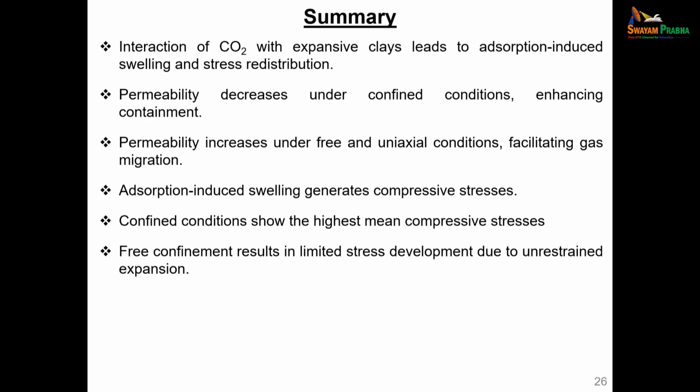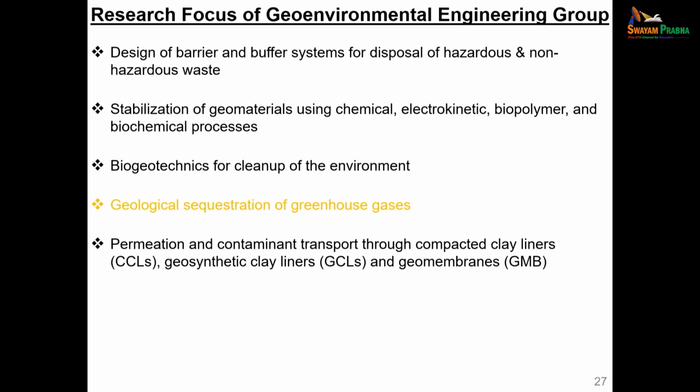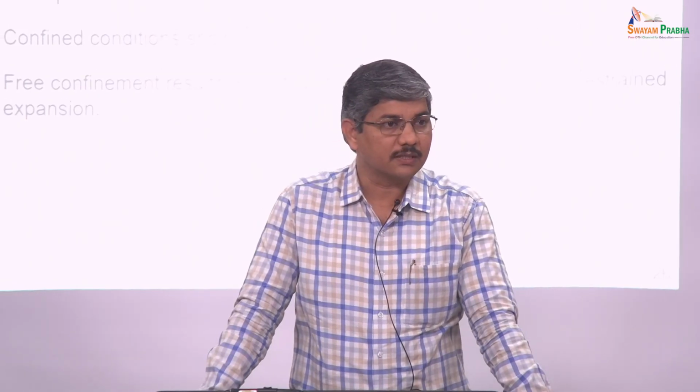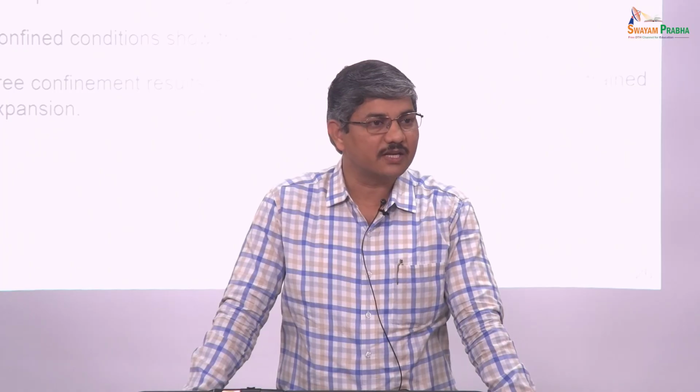So finally, adsorption-induced swelling generates compressive stresses under confined conditions. From the permeability point of view, that is good in the confined condition, but when you look at the deviatoric stress change, it may be a little bit of a counter effect. So overall, this is the story of geological sequestration of carbon dioxide. As a civil engineer, what we are able to do.